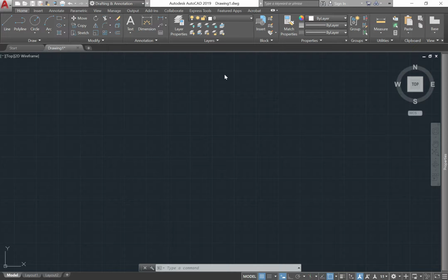And the next part that we're going to talk about is the info bar. In the input field of the info bar, you can type in a keyword, the name of any command or tool, to get more information about it for AutoCAD. You can simply type the name of the command and hit Enter to get help from the Autodesk help.